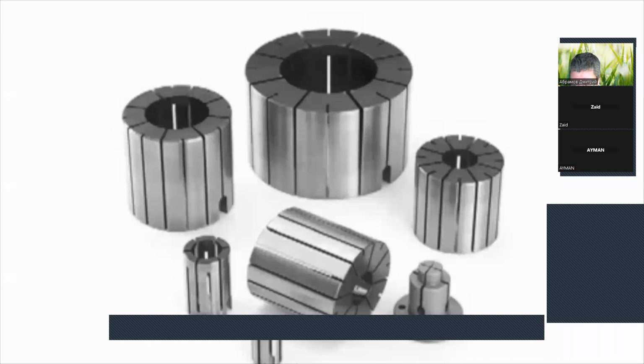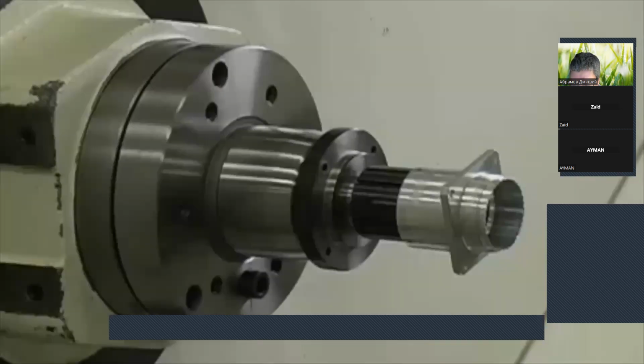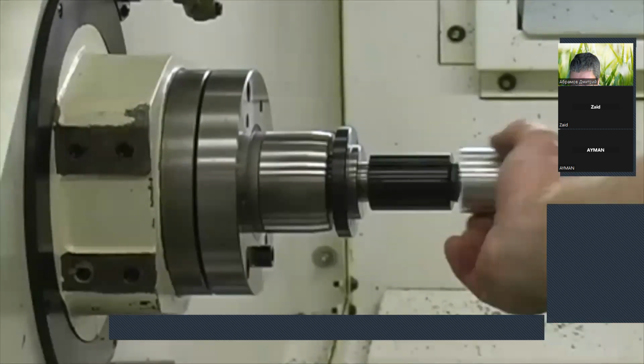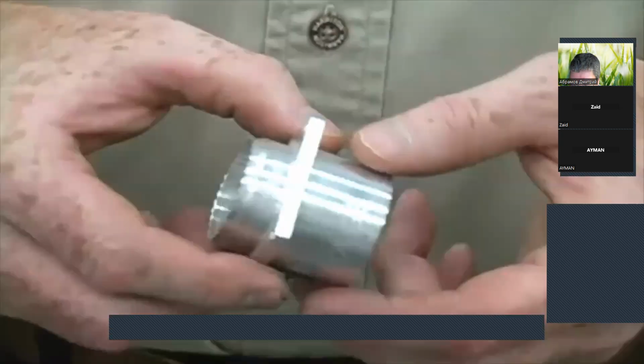The gripping range of each collet is plus 15 thousandths from its specified size. This part has an inside shoulder that positions it on the expanding collet. This example does not achieve dead length because the collet moves.